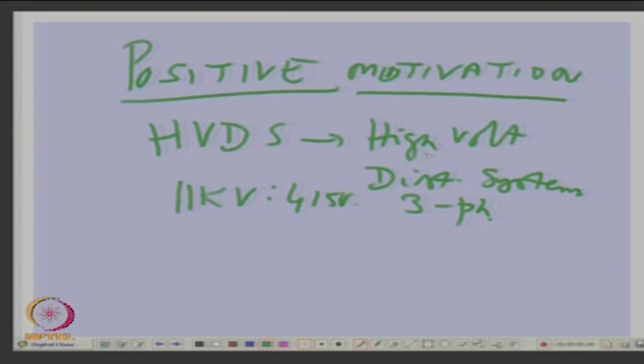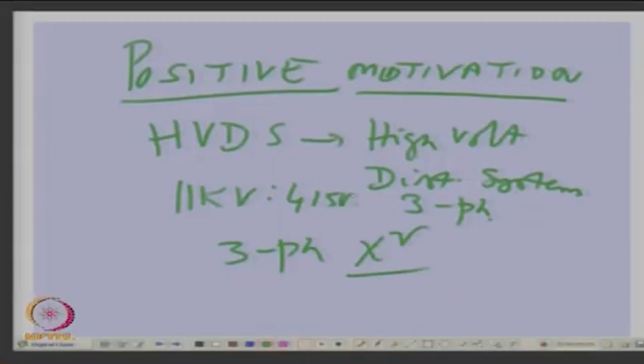In this case, distribution means you have to take thicker wires anyway for the same power. So, losses are high, and your copper is more, and since it is low voltage, tapping is easy. So, it is easy for stealing of power. Okay. Now, 3 phase is a problem because you need a 3 phase transformer, 6 winding and etc. Okay. 3 phase transformer feeding to 3 different houses, unbalanced and all these problems, etc.